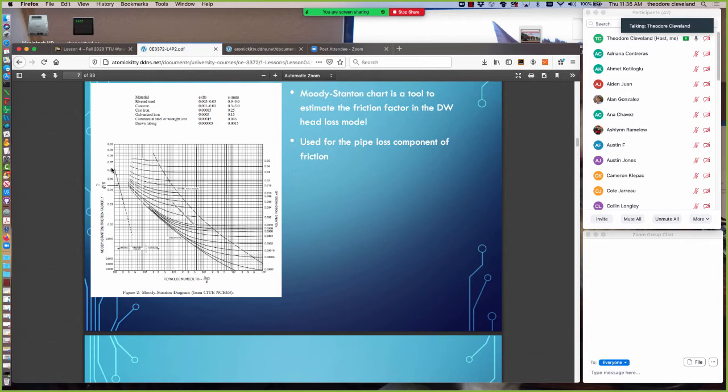Over on this part, if we know that the flow is laminar, the friction factor is by definition 64 over the Reynolds number. But at a Reynolds number between 2,000 and 3,000, this model becomes meaningless and the friction factors jump up to one of these lines. There's a fully rough dividing line here, which corresponds to the case where each of these roughness ratio lines becomes horizontal.